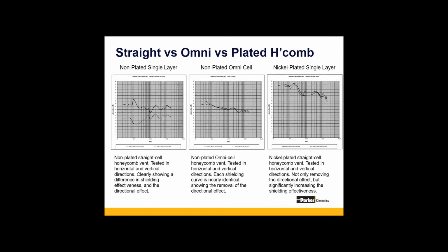Kevin, we've got a question from Pete asking, is there a minimum required or recommended angled honeycomb for privacy and EMI shielding? So there's really no industry standard for that. We have 30, 45, 60. Those are the three most common angles. 30 is the least dramatic, if you will, right? It's the closest to the normal straight cell.